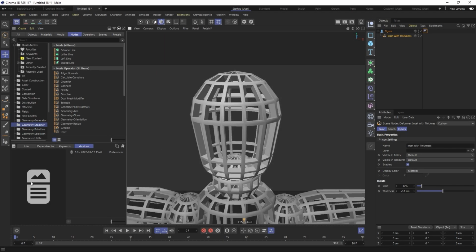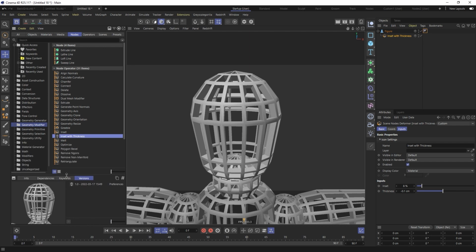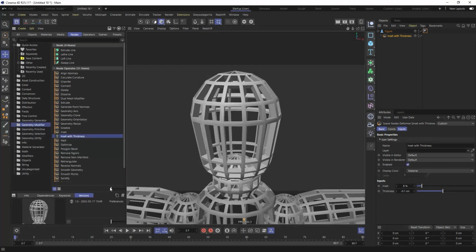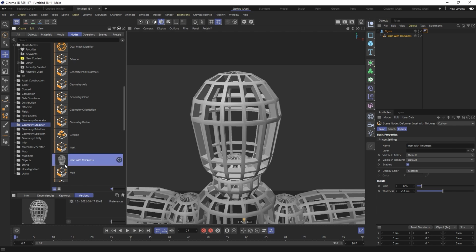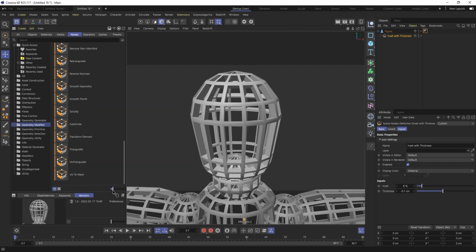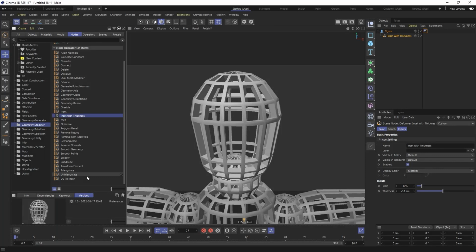And now if I were to right click on this blank icon, I could say Update Preview from Clipboard, or if you had it saved somewhere on your computer, you can update from a file, but I'll paste it from the clipboard and there we go. That is now the icon. And you'll even see if we get rid of that, that is an updated icon on the actual inset. So you could design your own ones really, really easily. And that just sort of completes out making this nice and clean and ready to be used. So just a nice way of completing the entire process of making that asset for myself.